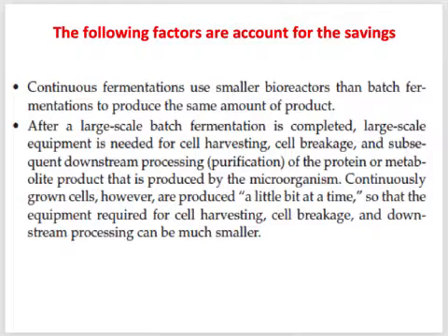If we use continuous fermentation process, we can use smaller bioreactors to produce a similar amount of product in comparison with the batch fermentation process. Suppose you want to produce a certain amount of your product. If you want to do it by using batch fermentation, you have to do it at once, right? That means your fermenter size has to be big. But in continuous fermentation process, we can continuously harvest some of our product, so that means we actually don't need a very big fermenter. So this is one merit.